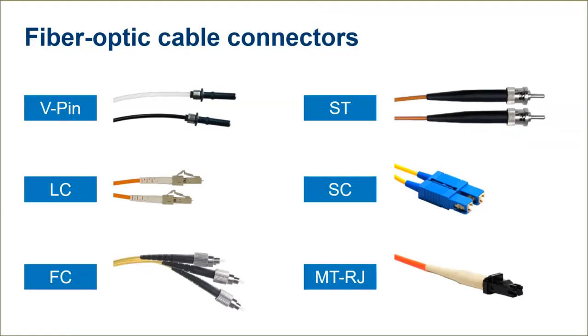They're used for multi-mode applications. They're fast, easy to terminate in the field, and they use a simple click-in design to terminate into the transceiver. Duplex latch kits are available for these applications, requiring latch retention of the connectors to make sure that they don't fall out.